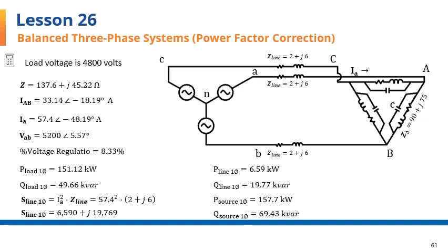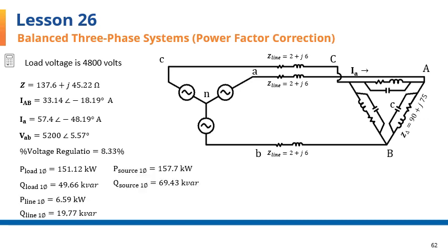And here they are. Summarizing those results to make some room here. Let's calculate the apparent power of the generator so that we can use it to find the system power factor. Again, Pythagorean theorem. S source equals the square root of the sum of the squares of the two powers, the real and reactive powers. And that results in 172.3 kilovolt amperes.